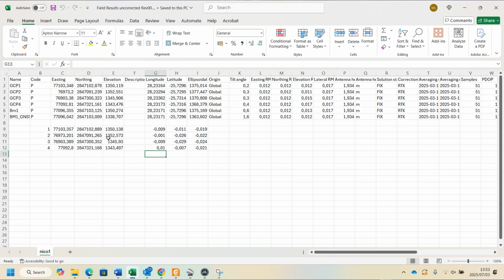Okay, so if I compare my GCPs with each other, so this is the actual measured coordinates from my RS2 Plus base and rover, and this is the actual coordinates that we extracted from 3Dsurvey itself. And over here we can actually see the residuals are really spot on, and that's incredible. So getting those type of accuracies on a drone normally was not possible, but we're very excited to announce that without any additional correction, we're able to achieve, like, the maximum on elevation is about 2 centimeters,